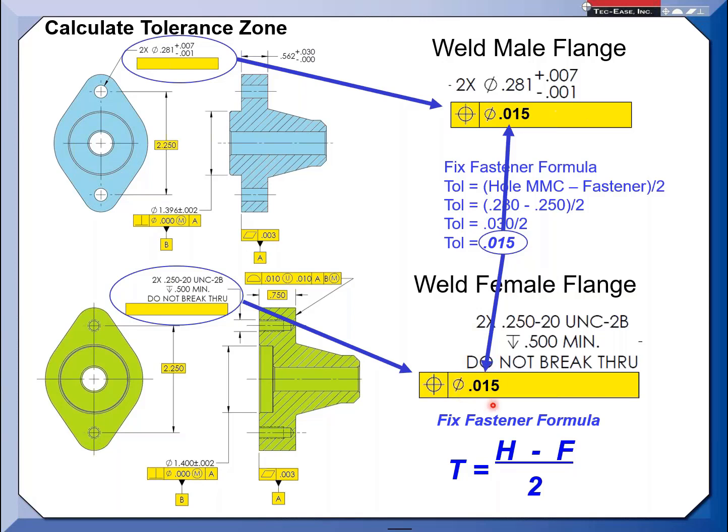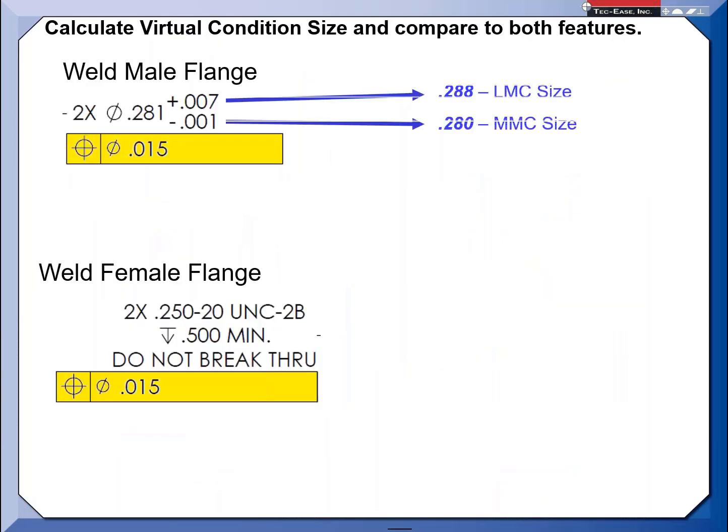Usually what they do is give a little bit more tolerance to the tap tools, because once you tap it, it's a done deal. And so they'll lean more. I've seen 60-40, 30-70, 1/3, 2/3. So depending upon the company, that's what they're going to wind up doing. But we were very specific: just do equal distribution. So over here, in this case, you can get the hole.